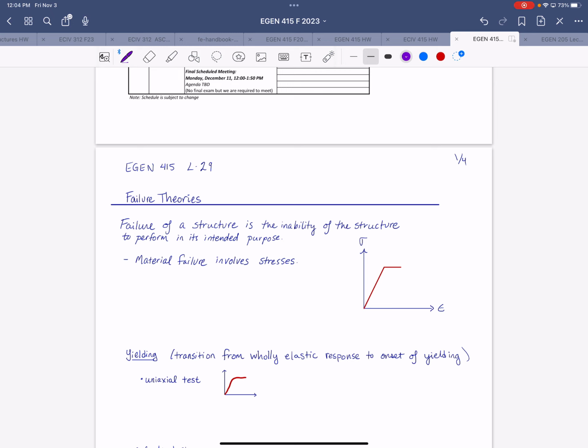In order to do that, you're going to have to apply a dummy load, because with the distributed load, we still don't have a discrete point force to apply. That's what the Castigliano's method, or the modified method anyway, is built upon: a discrete force or moment that you take the partial derivative with respect to, and that point has to be the same location where you are determining the displacement. Which we don't know, right? Right, we don't know where that needs to be, so that's another unknown in the problem.